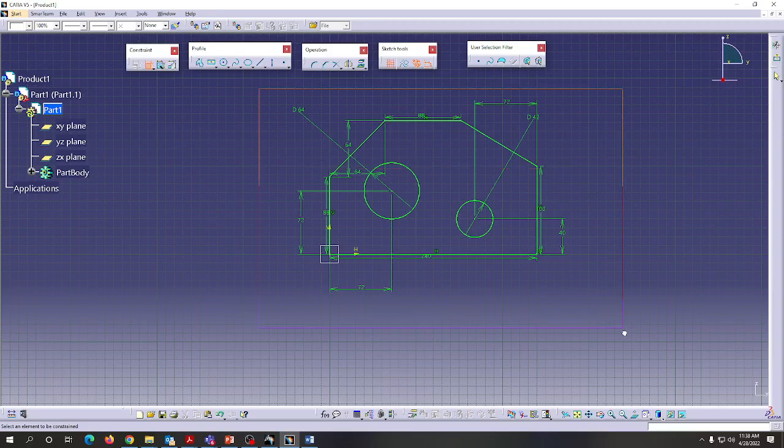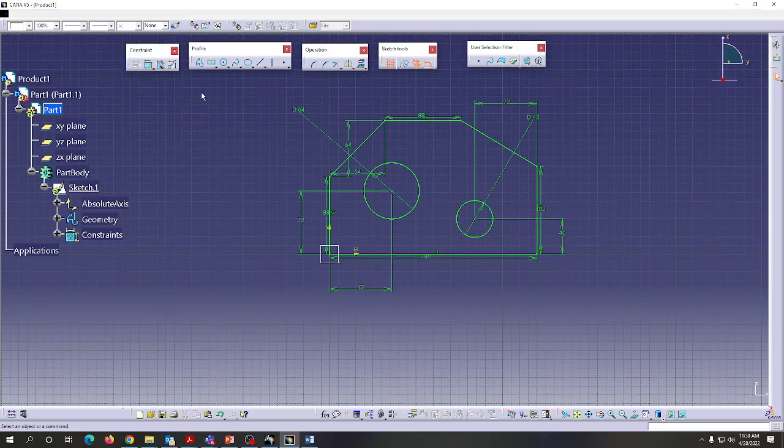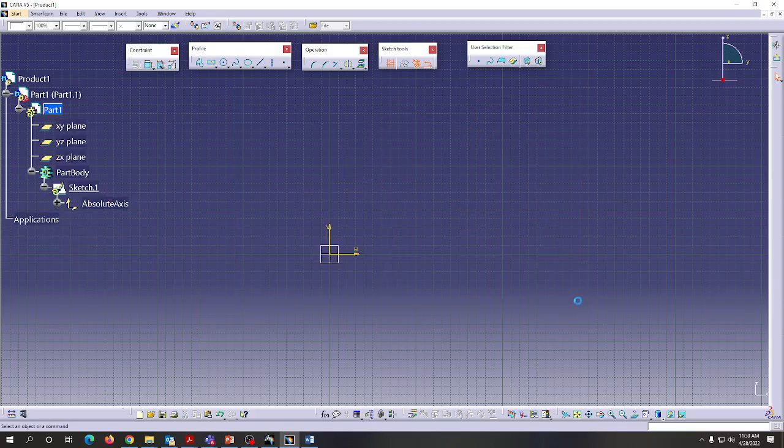So again I'm just clicking here, just dragging the sketch. Or we can click here also. I think it is constraint, it is not working. It's okay. Why is that command not working? Already we are in constraint command. This is very, very important. Once you finish the sketch, you have to come out of the command. Then only other command will work. Now I'm just clicking the sketch and deleting it. That's all.